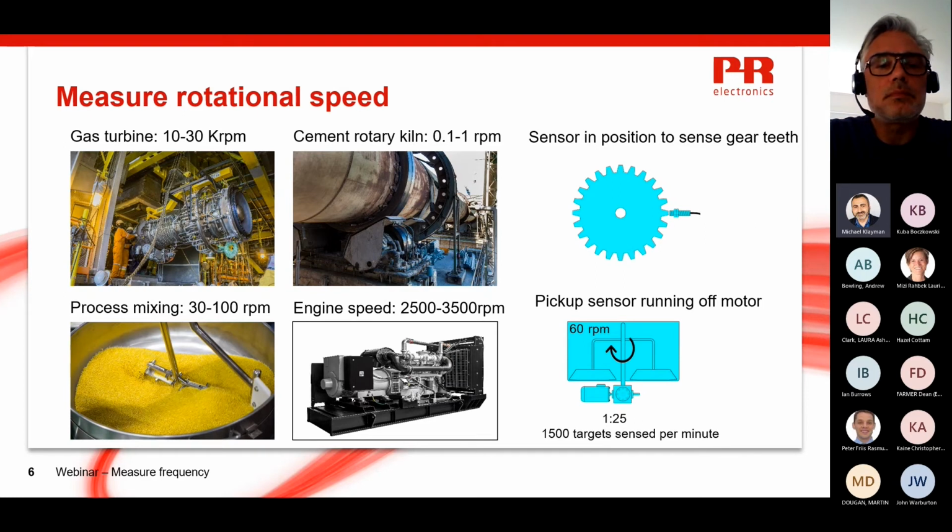The cam has a gear on it with 25 teeth, so each rotation makes 25 teeth pass by the sensor for every one rotation of the shaft. We can say that this cam has a ratio of 1 to 25. For every one shaft rotation, the sensor sees 25 targets. Thus, we are measuring 25 times more signals than the amount of times the mixer revolves.